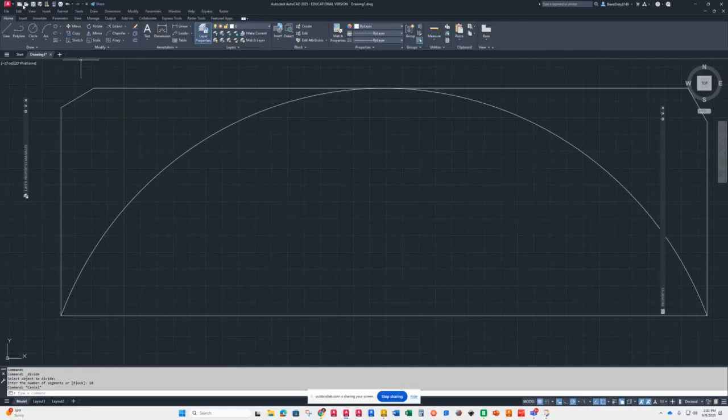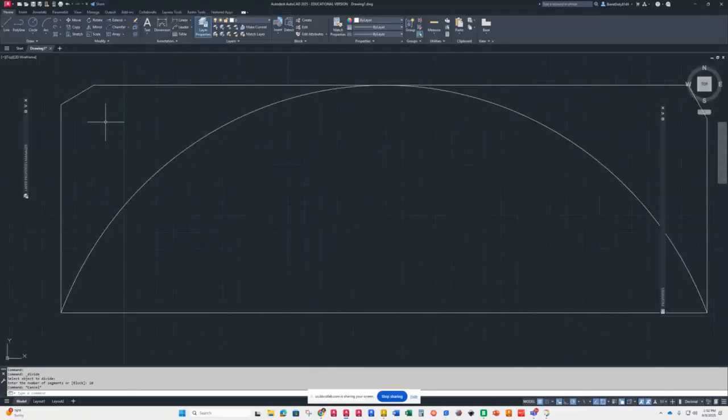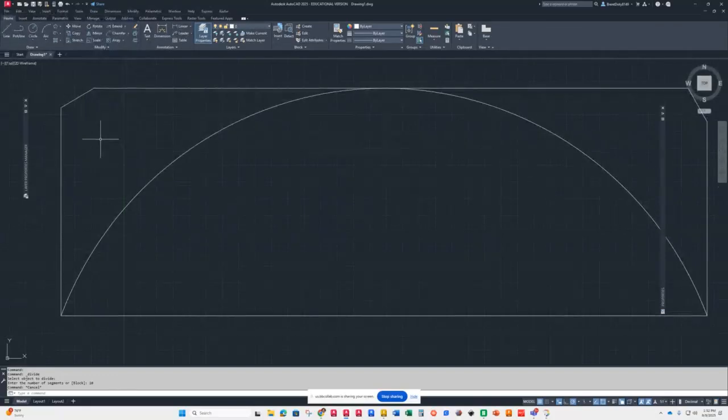If you go up here to your quick access toolbar, you go over to the end of it next to where it says share, and you got the little paper airplane. You click on the little down arrow and you get what you can turn off and on to make visible, right? Well, one of the things that you can enable is the menu bar. It's the next to last one on there. You'll notice mine says hide. Yours would say show. So if I click on it, mine goes away. No, I want that back. So I click on that again. I click on show menu bar. Now I've got a menu up here.